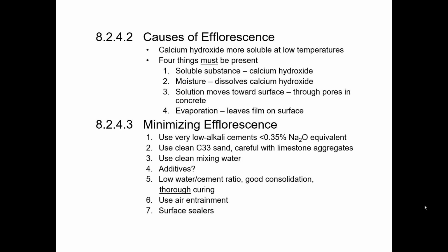There are plants out there, and different states have different incentives for recycling wash water and using less water. While that's overall a good thing, you definitely want to make sure the right checks are in place to make sure that water is still acceptable if you're using wash water. There are limits on different particles and contaminants that can be present and it still be allowed to be used. So some of these calcium hydroxides may be present in your wash water if you're recycling, or even if you're getting it from a municipal source. Sometimes things happen there as well. So make sure you know the quality of your water.